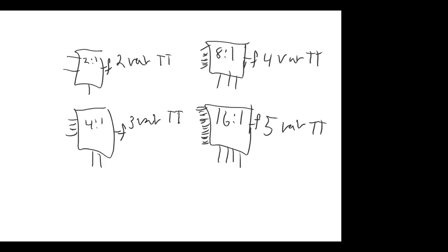The 74150, that would be your 16-to-1. The 74151, that would be your 8-to-1. The 74157, that would be your 2-to-1. And the 74153, that would be your 4-to-1.